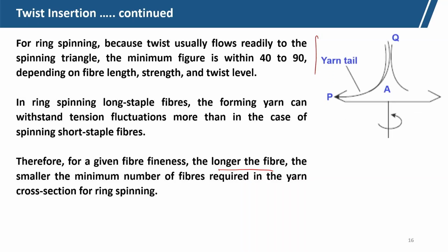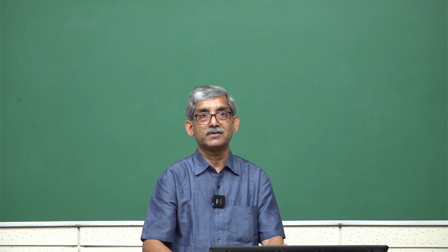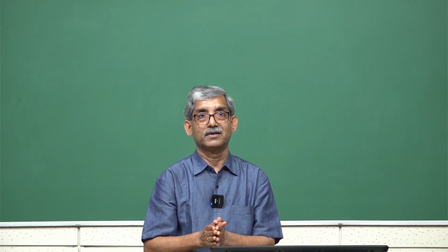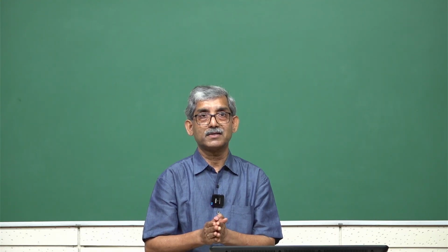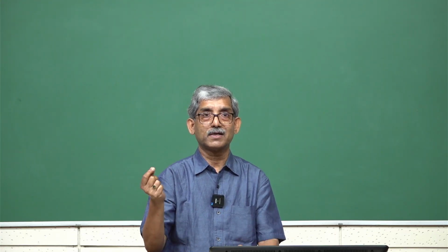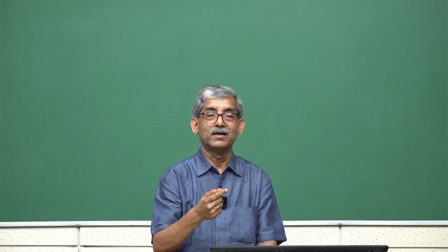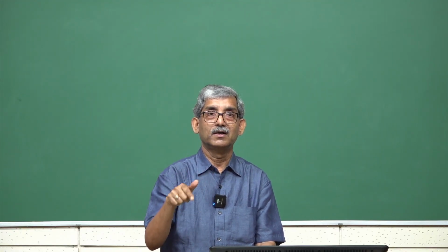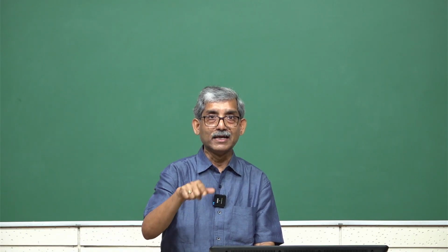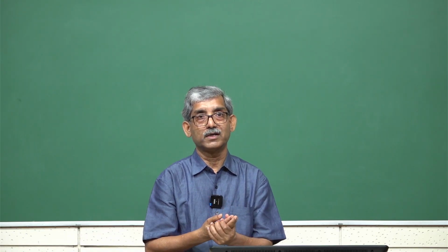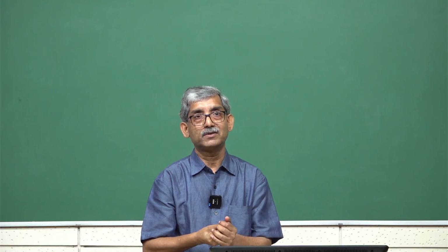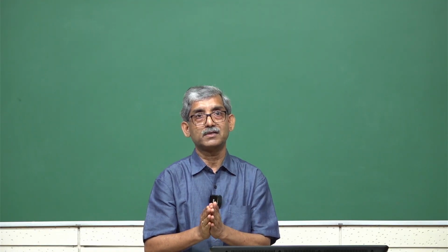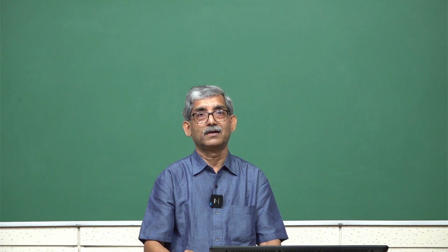Okay, now we will stop here. In the next session we will discuss rotor yarn formation by cyclic aggregation. What is cyclic aggregation? The fibers land one by one, forming the yarn in a cyclic manner as the rotor is rotating and peeling is taking place. All these issues we will discuss in the next session. Till then, thank you.